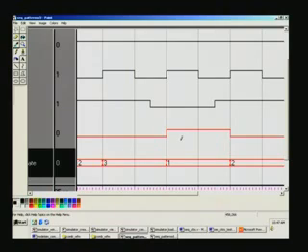So if you look into the source code, Verilog code, you will see that. So we would have put always at positive edge clock. So only at the positive edge clock all this happened. So this was earlier in the second state. At that point of time, only at this stage it is taking from 2 to 3, and right at that point, whatever is the actual input here, only that is being taken and then processed accordingly. So in order to enter this here, you had to satisfy this previous condition. So also here. So in order to enter the next state, you had to create a favorable condition for the input.